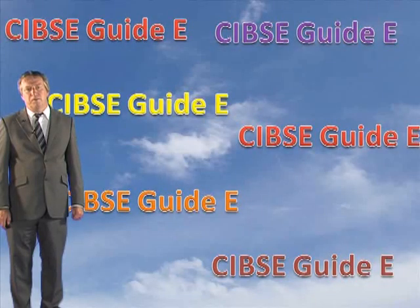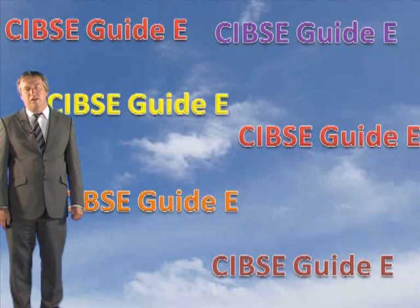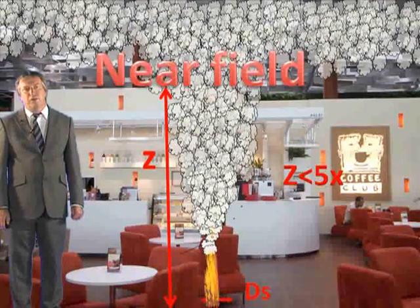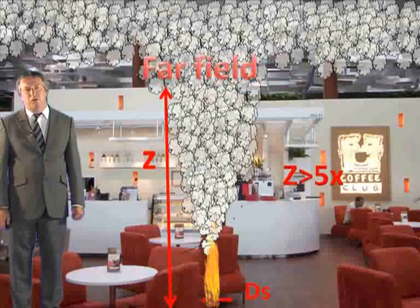In the Fire Engineering Guide SIPSI Guide E, the advice is to use the far field equation exclusively, whatever the value of Z. Some people feel that the values for mass flow rate by the far field equation for values of Z less than 5 times the longest dimension of the source fire are smaller than would be expected in reality. The best advice is probably to stick with the near field model for values of Z up to 5 times the longest dimension of the source fire, and use the far field model for values of Z above this. Now let's start by looking at the near field model first.